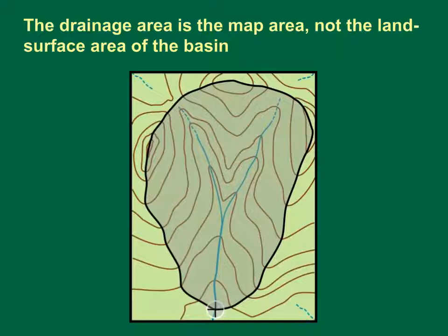In some areas, particularly in small basins and at highway sites, storm sewer drainage systems may divert storm flow from one topographic drainage area and divert it to another. Use of topographic contours of about 2 feet and manual inspection of drainage basins may be necessary to delineate basins on the scale of a city block in areas with storm sewers. Differences between natural topographic divides and anthropogenic divides can be substantial even in relatively large urban basins.